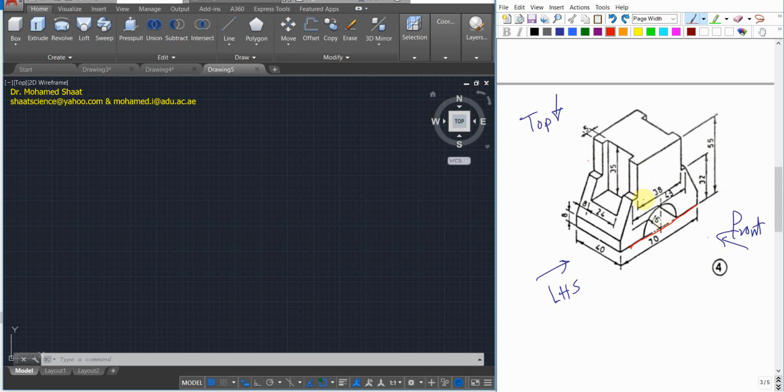Like the first step, first of all, we're just gonna assume that this thing is closed and we're gonna extrude it, and then we're gonna subtract this hole and we're gonna subtract this opening here, right? And this is the thing that I'm gonna do first. Then I'm gonna give you another approach that we can skip one of these 3 steps, instead of having 3 steps like building extrusion then 2 subtractions, we're gonna have 1 extrusion and only 1 subtraction.